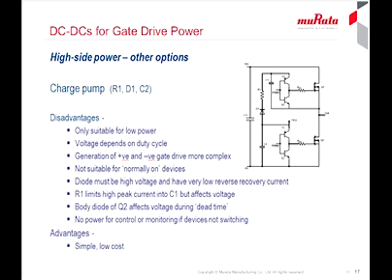D1 is also a critical component for reliability. If it fails, the driver for Q2 will be destroyed, possibly along with many other components.